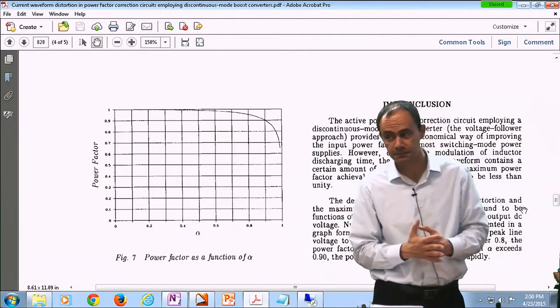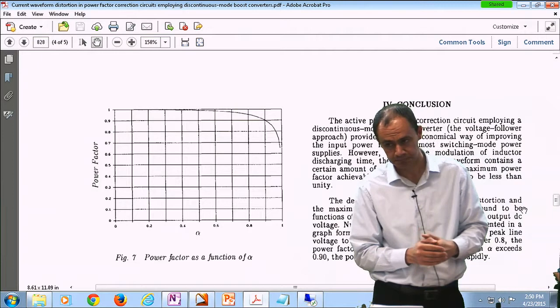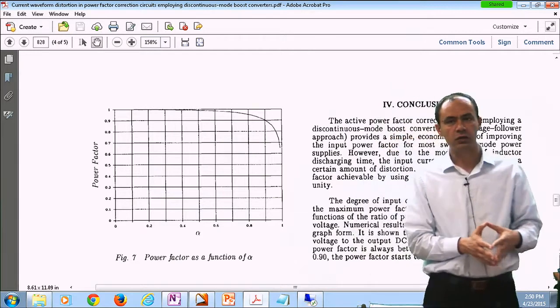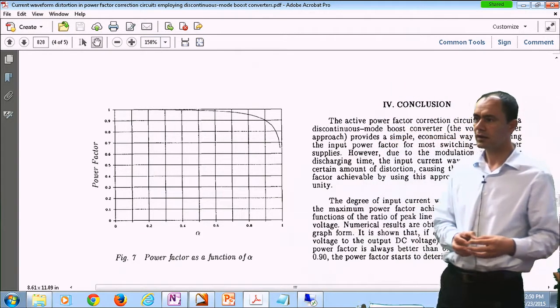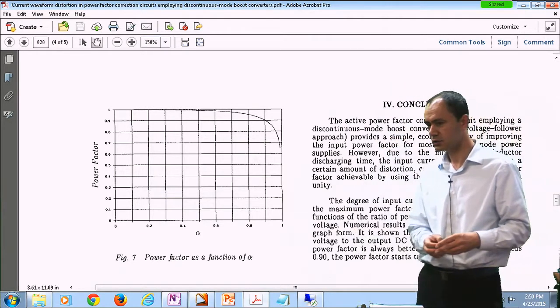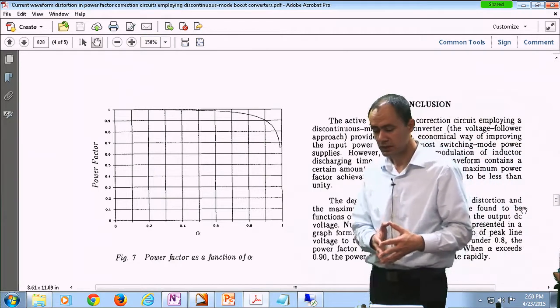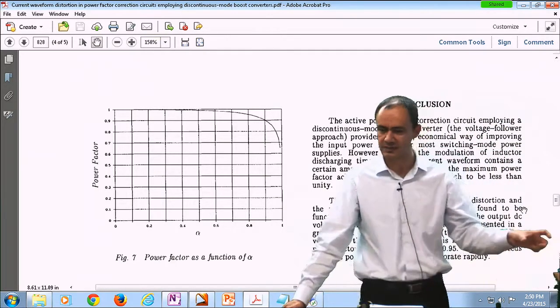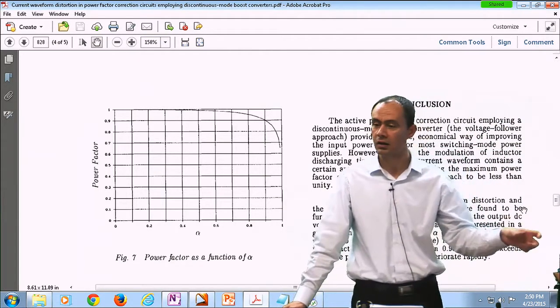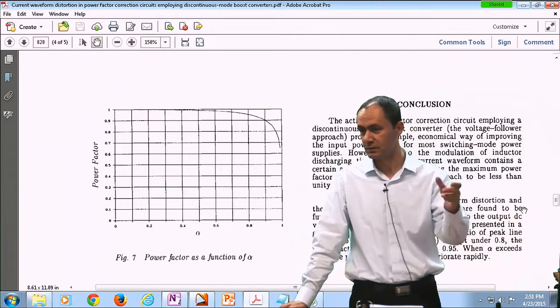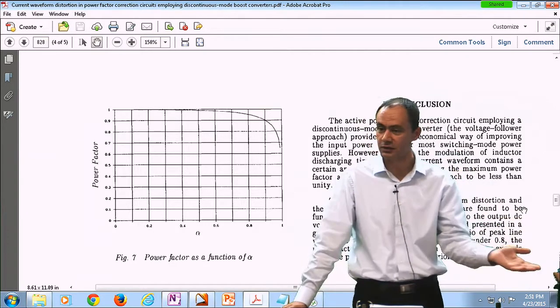Any questions? Yes. So if you needed a lower output voltage, you can implement a flyback converter with a buck? You mean lower than the peak value of the input voltage? Right. In a double stage case, you can cascade another buck converter after this to step it down from like 240 to something else.